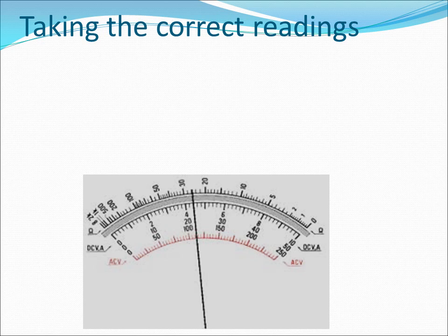For instance, if I take the ×500 scale, the maximum reading I can do is of course 500. But any reading for DC voltage must now get a 0 added. Therefore, the needle where it is at this moment will indicate 220 volts on the ×50 scale, because maximum voltage on this scale and this setting will then be 500 volts. You can now apply this principle for any scale you use.